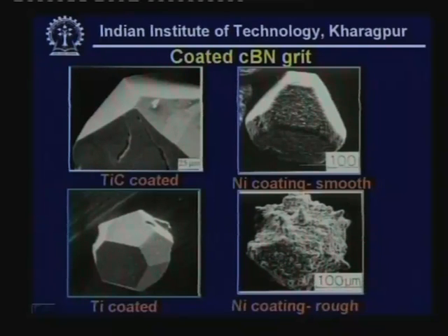Normally, the metal bond cannot provide good adhesion with a bare surface of CBN, which is chemically very stable. The metal cannot have very good adhesion. For augmentation of this adhesion, we put either a metal or a hard metal, TiC or Ti. This goes well with a metal binder, metal bond. But vitreous bond is also one successful bonding system with CBN.